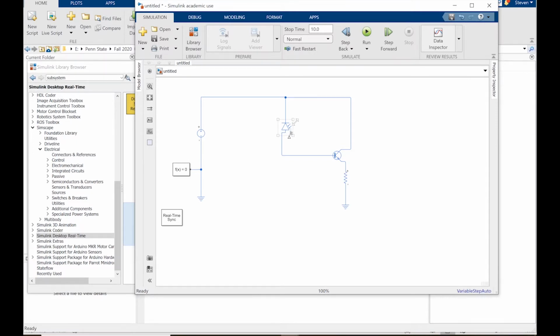So here, the amount of light. As more light shines on this diode, which is in reverse bias, here we have the cathode up to the positive voltage, and the anode going down to the base of this transistor. So the more light that shines on this, or the larger number we put into this signal port, the more this conducts. So the more that this will actually bring this transistor up into saturation. So once there's enough light that will allow current to flow through this into the base of the transistor, the closest we'll get to saturation. We're not going to fiddle around with it too much in the simulation. You can add resistors to the input, like a voltage divider, so you can bias it, and you can control basically where the switching point is. Let's make that a little nicer.